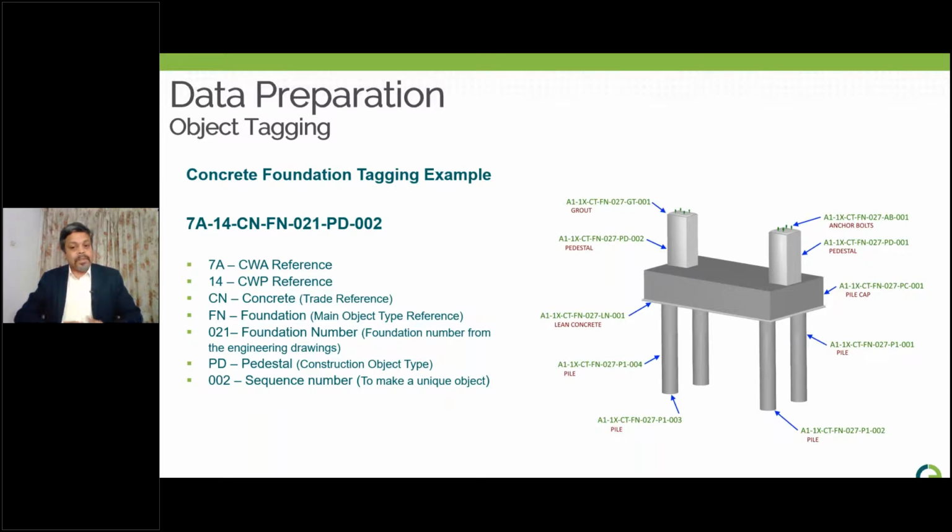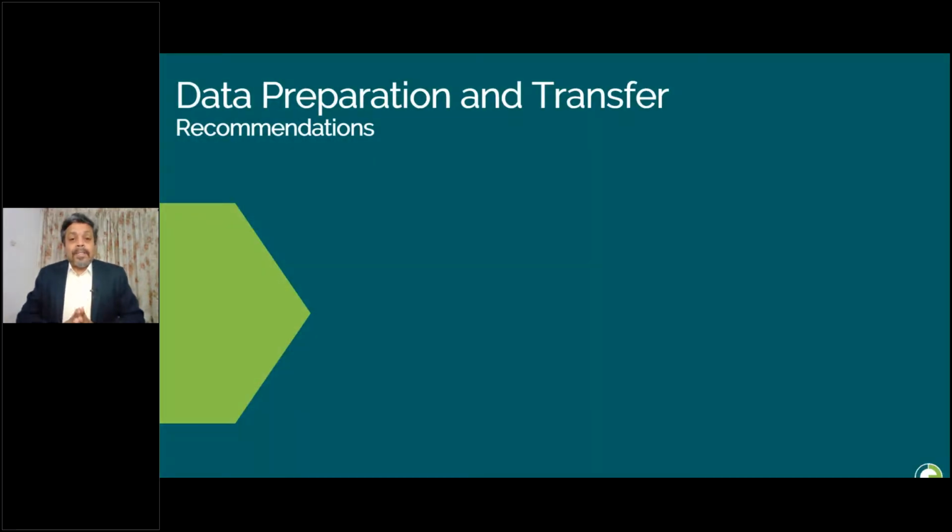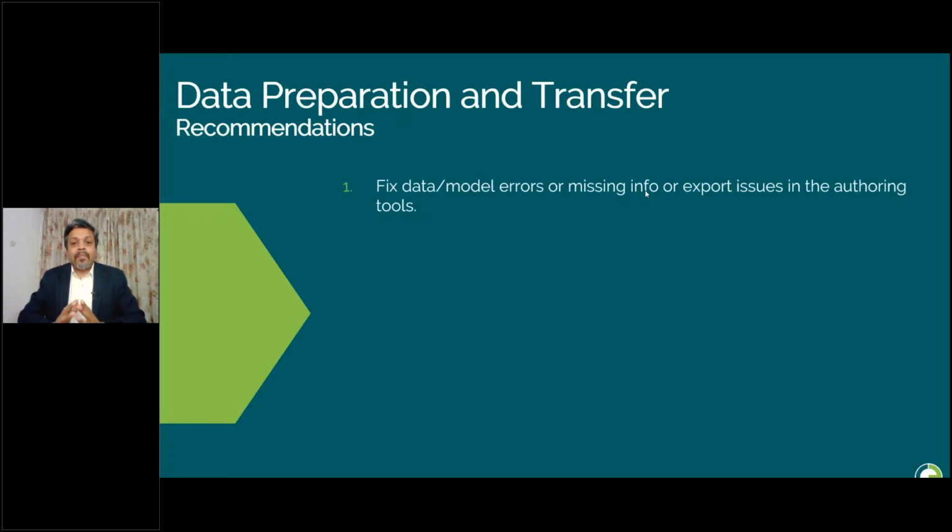Next, before I close, I will discuss some tips for data preparation and data transfer. Data preparation and transfer: these are general recommendations based on our experience and some of the best practices that we always follow. Fix the data and model errors, missing info, or export issues in the authoring tools.